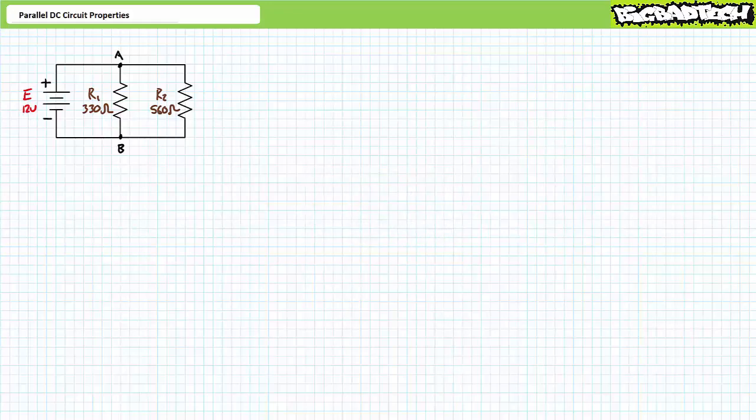A circuit is a complete path or a closed loop. The closed loop could be a single circular, rectangular, triangular, or any other shape forming a complete loop or composed of many different pathways, at least one of which connects one terminal of a voltage source to the other. Without at least a single closed loop, there is no circuit, and there is no way conventional current can flow from the positive terminal of a source to the negative terminal. A closed circuit requires a closed path for current to flow. Circuits consisting of multiple resistors can assume numerous different configurations, one being known as a parallel or side-by-side configuration. A parallel arrangement means there is more than one path for current.